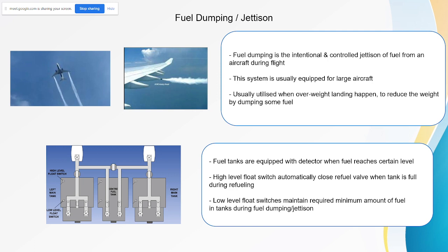I think it's using the differential pressure and also the gravity, because the wing creates a pressure difference between inside the tank and outside the tank, so the fuel definitely will rush out. Right. So the pump will not be required for this system. Sir, don't require any pump. Correct. You need a valve to open and close only. Alright, thank you, sir.